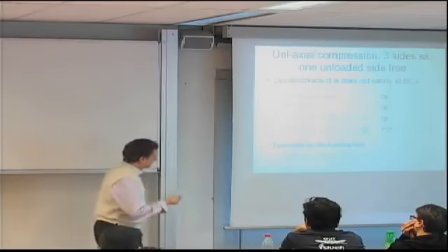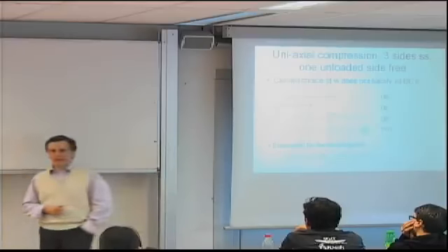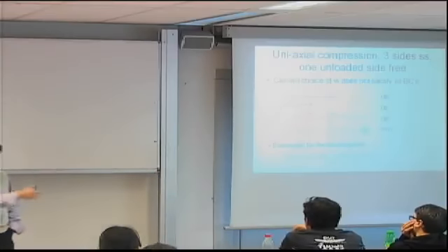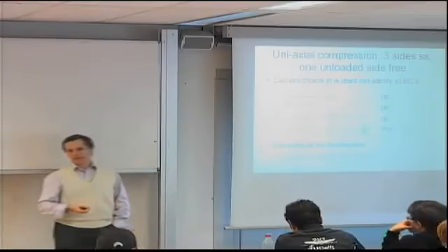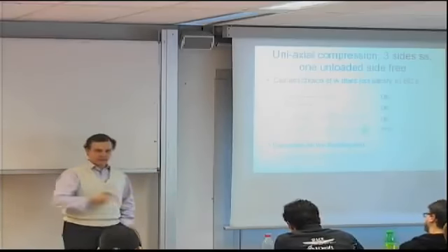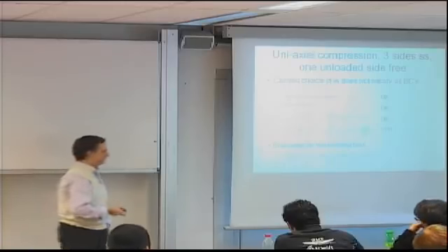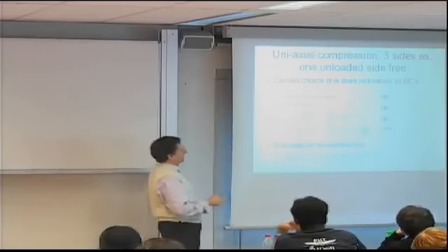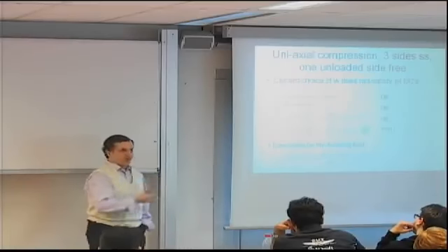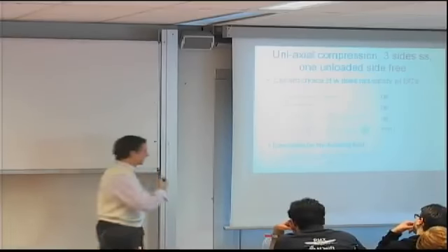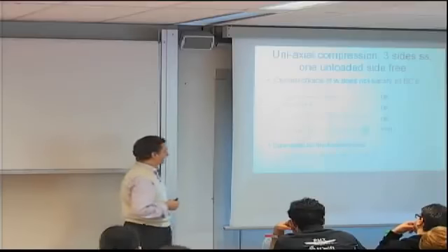So this boundary condition on the moment is not satisfied. So we have a residual bending moment there. And that tells us that the solution won't work very well, how well we are about to see. It's an approximation because even though you're trying to satisfy the governing equation, and in fact you picked functions for this W that will satisfy it, you are not satisfying exactly the boundary conditions.